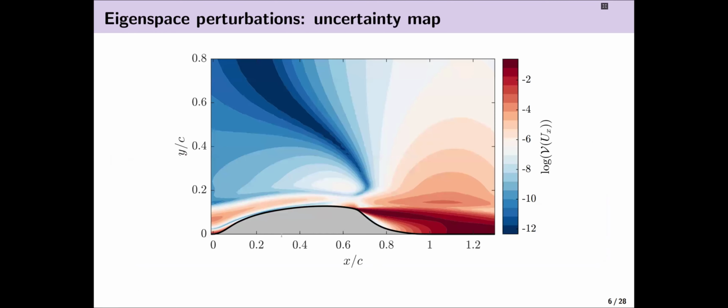For example, we can look at the streamwise velocity. Here I'm basically plotting a contour of the variance of the streamwise velocity predictions using the 5 perturbations and the baseline model. We can see that the highest variance uncertainties are in places where the flow separates in the boundary layer, for example, whereas in the free stream away from the hump wall, we have low uncertainty. So now we have this map to use and concentrate our sensors around places where we think it's highly uncertain.